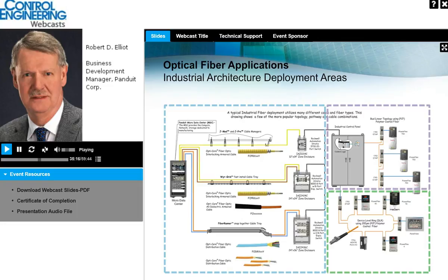This diagram here shows fiber in the different ways that it is available. And I'll just talk about the left-hand part of this. You can see the top horizontal run is showing an example where the armored fiber is used and is supported by J-hooks, for example. Very often these runs are made across the ceiling, supported. The pathway itself is comprised of J-hooks spaced at regular intervals.